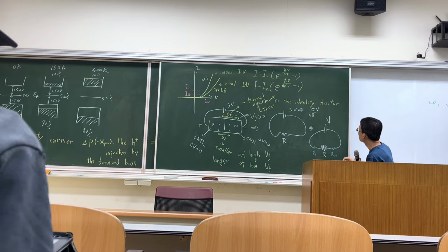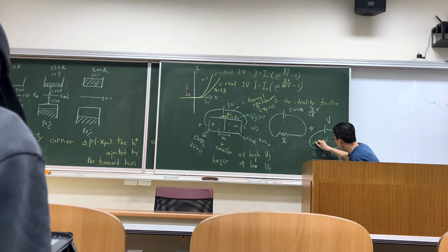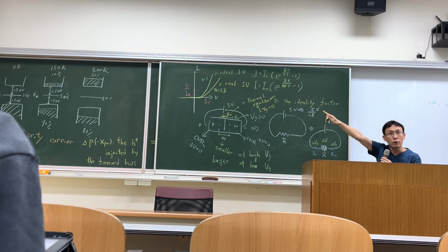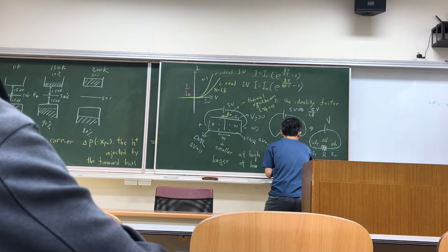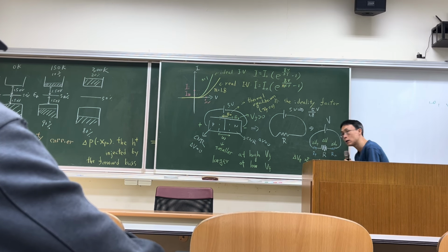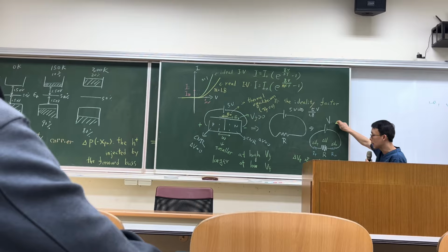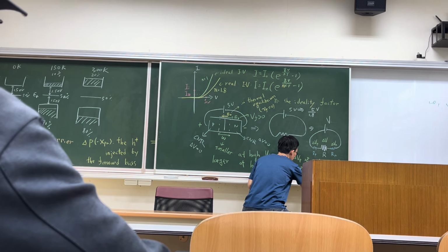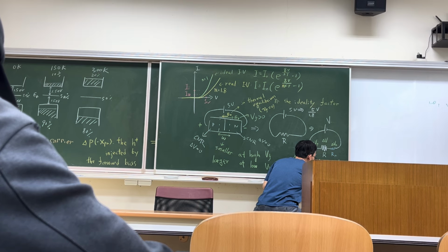So this is the V, and at the low bias, you have a voltage drop here, a voltage drop here, and on the p side. So for the IV curve at high bias with n equals 2, delta Vp and delta Vn are no longer 0 at large V. But delta Vp and delta Vn are equal or close to 0 at small V.